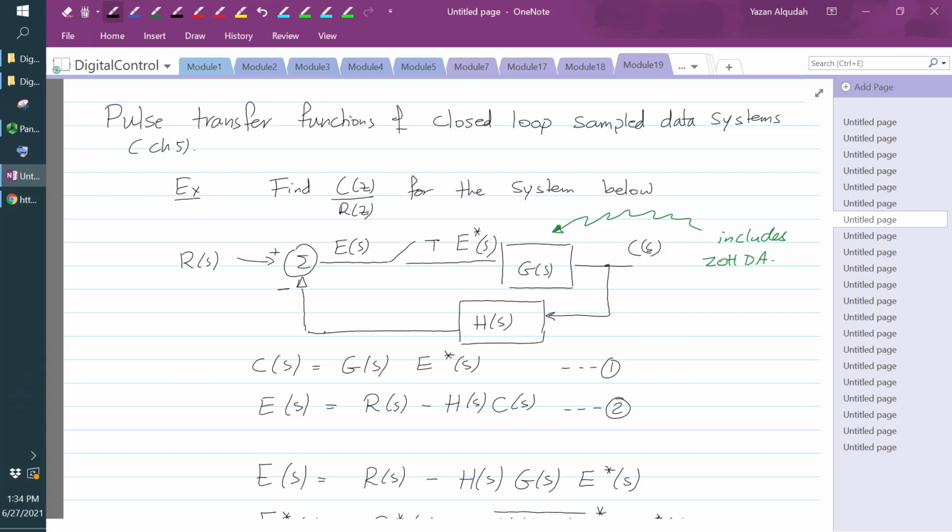Somebody might look at one configuration and say, why would you want to input this signal, sample this signal, convert it back to a continuous time signal and then put it through the system? Why would you do that? Again, we've done it here up to this point just to illustrate the calculation, but later on we're going to be adding a filter in between that will alter that signal before it is converted back to an analog signal.